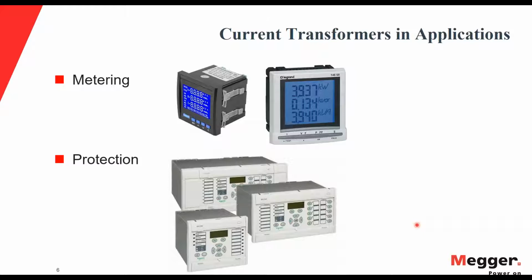So I need some accuracy, not that much, some accuracy that I can work with in the fault range condition without spending too much money on my CT or too many resources on it. So the classification of protection type CTs is based on this requirement, having a high range of acceptable error, like 5% or 10%. It's also considered an acceptable error in a protection system, and also compensated for in the settings of the protection system itself.